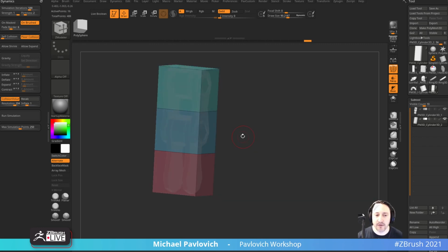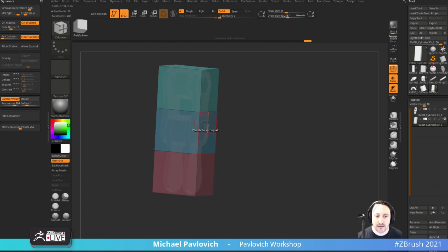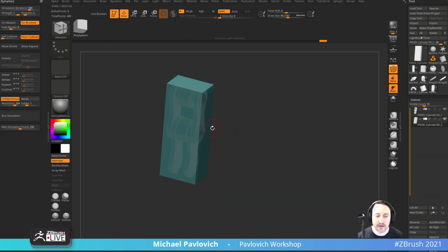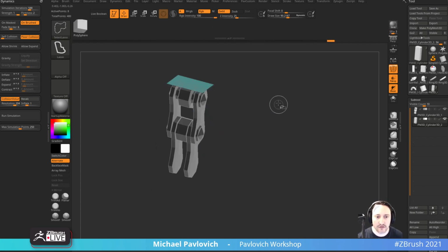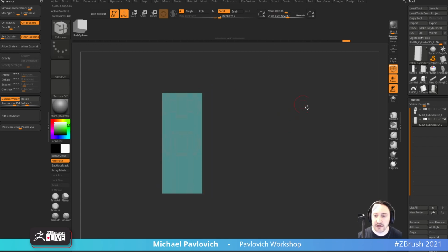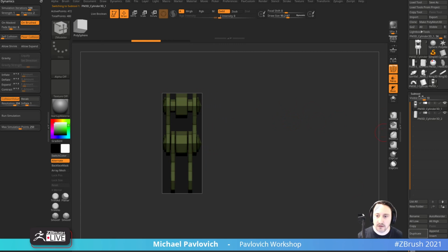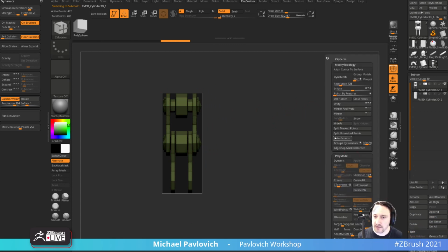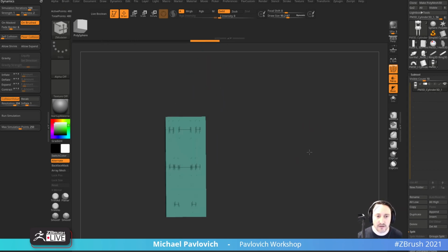I mean, I guess at that point, the game res actually would be insert. It would be this. So if you don't have a repeating middle, one thing we can do is we can say, okay, every bike chain is going to have this as its game res geometry. So let's go ahead and merge these down. So Control W and then say merge. Control E. So we have our game res and our bike chain.